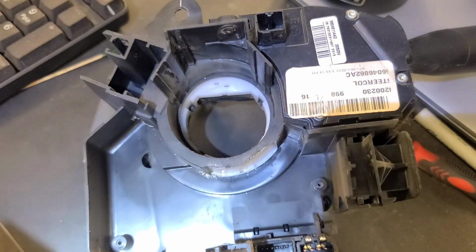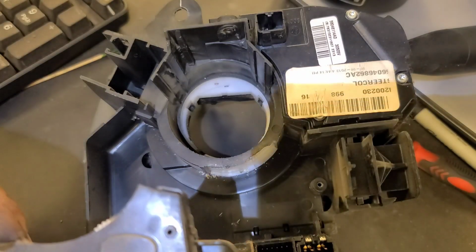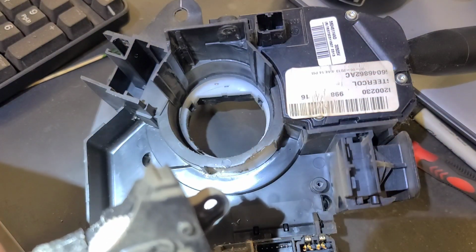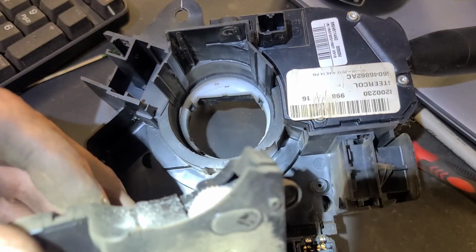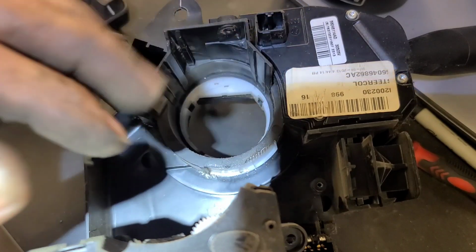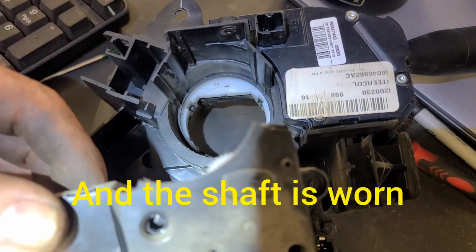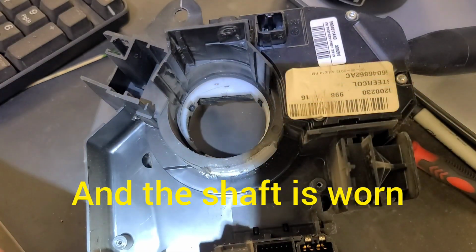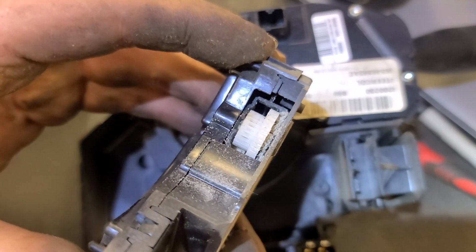Well, those are T10 screws with a safety Torx bit. And I have a kit that I bought on Amazon a few years ago, but I see what's caused the problem here. This little sensor is gear driven off of these teeth here, and the plastic teeth are worn. That's the steering angle sensor, this piece right here. And there's no point me trying to re-index this because the teeth are worn out. You can see the plastic material in there.